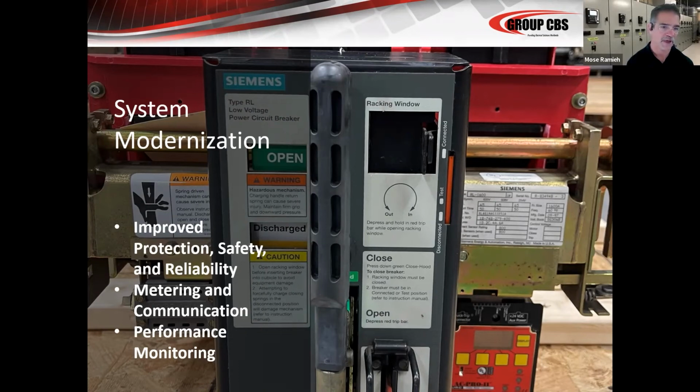And then going back to the question about, hey, where is it written, 3 to 5 years? Most of your manufacturers do have some references in their literature that there is a routine maintenance cycle they recommend, and it typically falls in that 3 to 5 year window. NETA has a matrix, and that matrix basically takes into account the criticality of the equipment, the age of the equipment, and the condition, right? So if you've got a data center and you've got controlled spaces and your equipment's relatively new, you might be able to extend that maintenance cycle out more towards the 5-year portion.